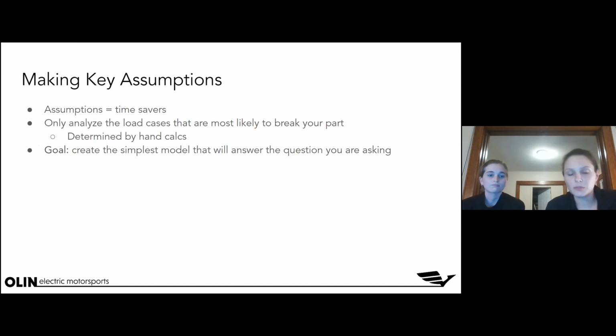So assumptions are really important because they are time savers. In a perfect world where time is not a constraint, you could do many different analyses on every possible load case, but that's just A, not necessary, and B, as I said before, way too time intensive. So you're trying to pick the load case that is most likely to break your part, as Katya was just saying, which you can determine by hand calcs, and just do that case or those cases.